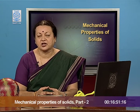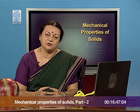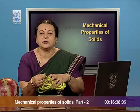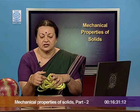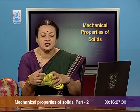Now, these were such which depended upon the nature of the solid structure, and therefore, you categorize them into three classes. We said if the solid has more length like the rope, then you would be talking about tensile deforming force, and consequently, the restoring force which developed inside it per unit area, you called it stress. The measure of how much of deformation took place along its length was longitudinal strain.